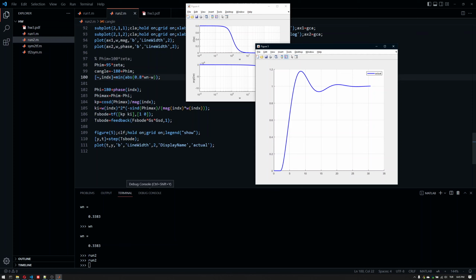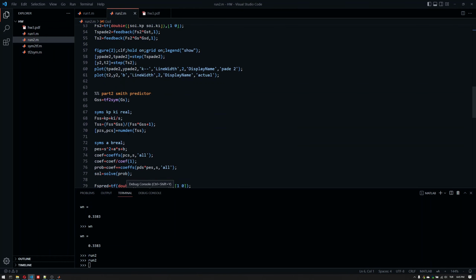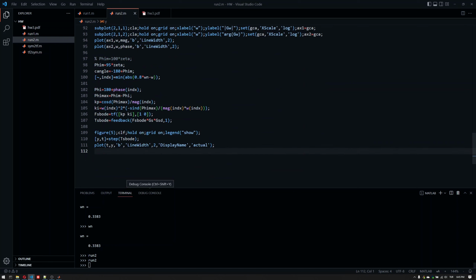And the reasoning behind that is we have a high order system, and not only a high order system, we have also delay in the system. So these methods using the Bode plot are not really suitable for any system, because you might need to tweak it a little bit, and it has its limits, because we have only a Bode plot and we don't know what the Bode plot belongs to. It could be an aircraft, it could be a vehicle, it could be something else, it could be the human body. We don't really know when we have a Bode plot and only the Bode plot, and the design methods that rely on the Bode plot are quite struggling with the system.